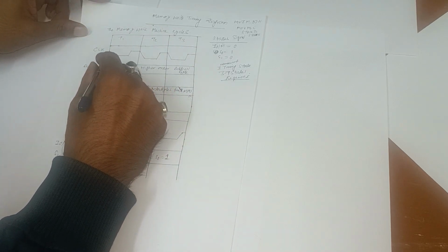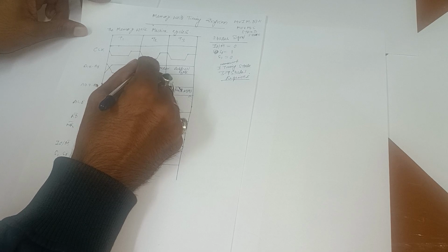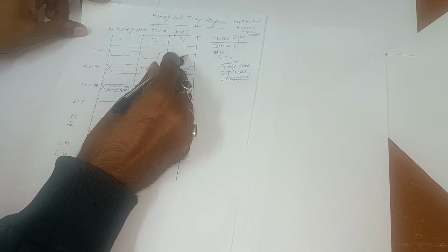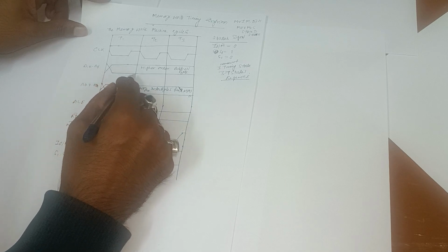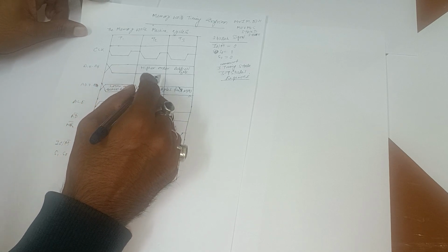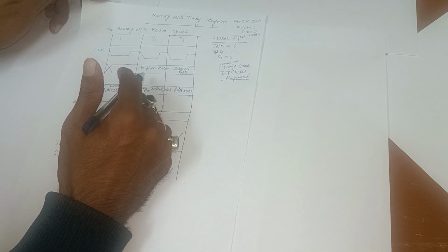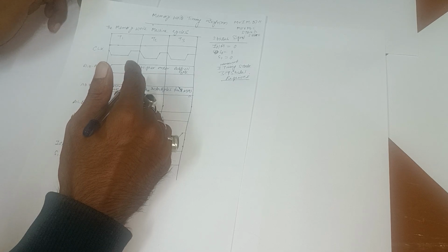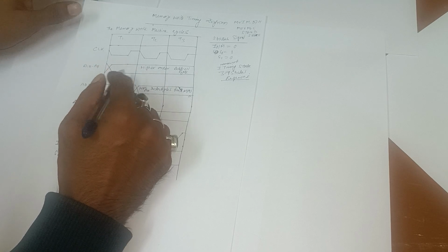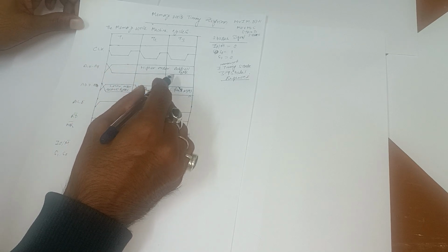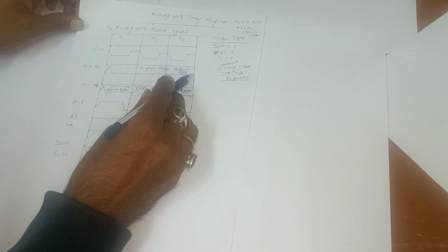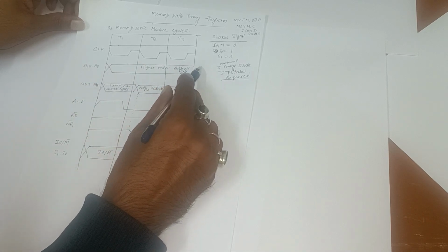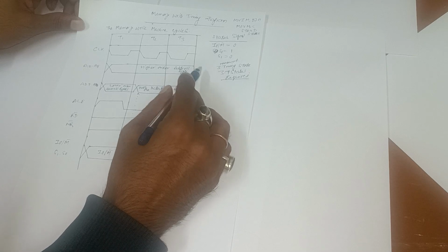In the clock, again we have taken the clock pulses. The frequency is for a particular time period. Now A8 to A15 you can understand very easily, because in the previous lecture I told you about the timing diagram of code fetch and memory read. Now memory write will be much clearer for you. This is again the higher order address byte. So in the T1 to T3 region, because there is no T4, undefined is not needed here.